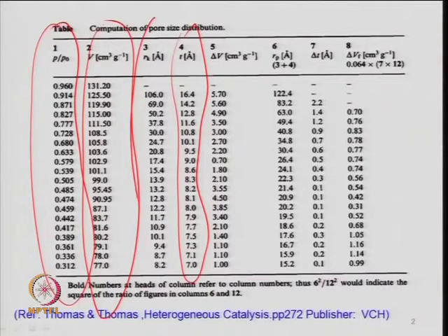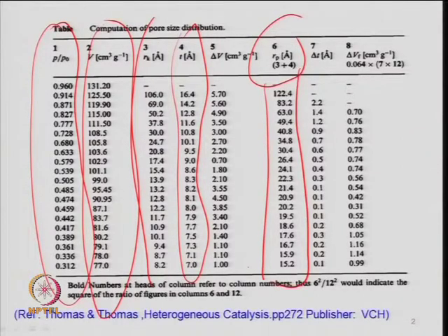So, r_k is the Kelvin radius here. This Kelvin radius, as I said, is less than the actual pore radius. So, that is to be added, and you get the pore radius here. This is your actual radius of the pore, which is used to determine the pore size distribution, or that takes part during the catalytic action.